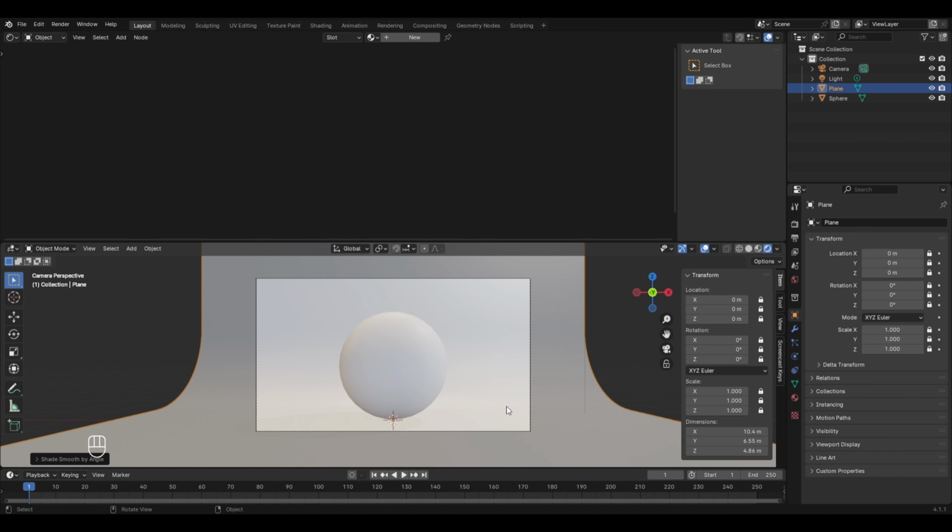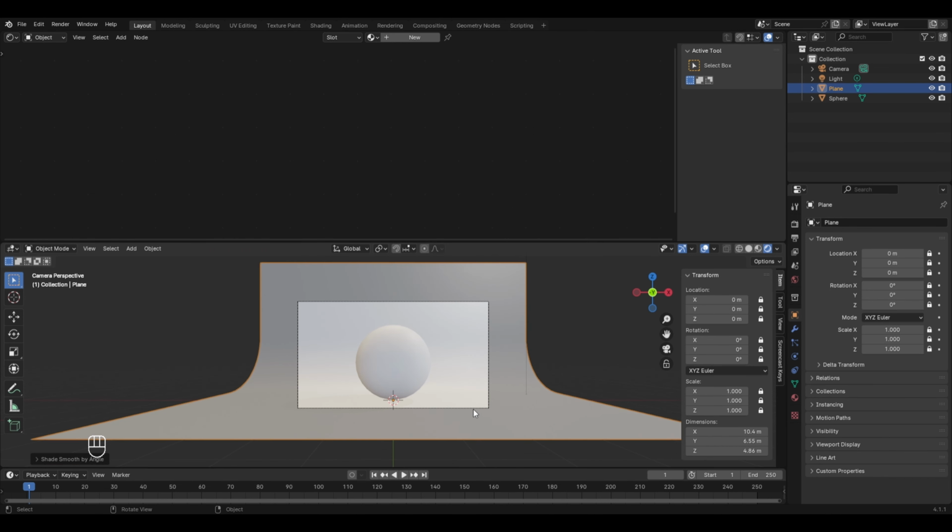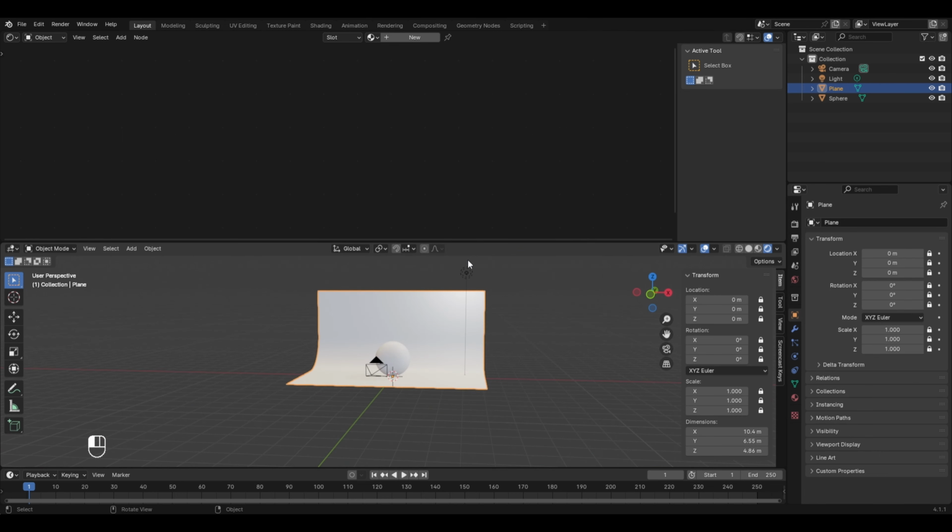And now is the time to adjust the lighting. So if I zoom out and select the lamp here, with a left mouse button click, I can move it by pressing the G key, and you will see the influence of this light on your object and the surroundings as well. So I think that we should place it here.